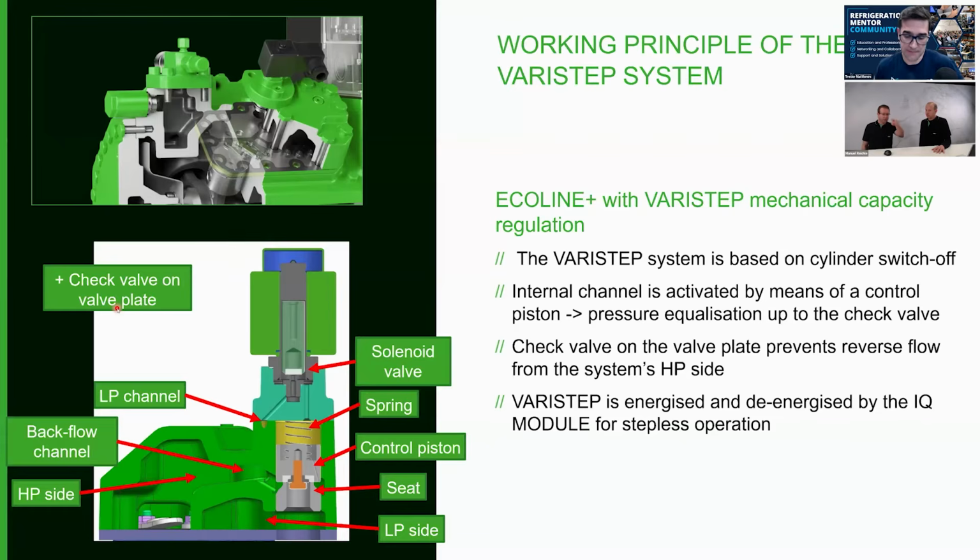Secondly, because we run it in this internal loop, there's not really a big mass flow, so in a lot of cases the valves will maybe not move. When it's unloaded, which is also important for the efficiency later on, it's really only the mechanical wear of the drive. There's not really compression work done.